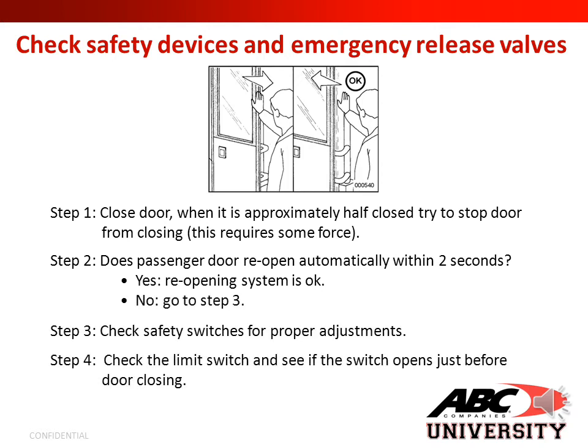Check safety devices and emergency release valves. Step 1. Close the door. When it is approximately half closed, try to stop the door from closing. This will require some force.